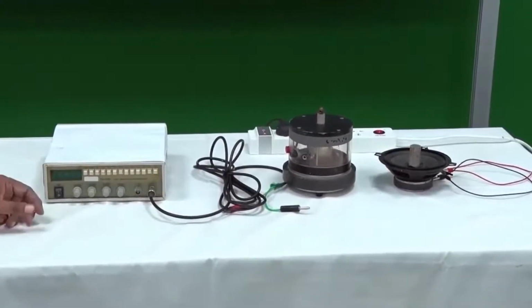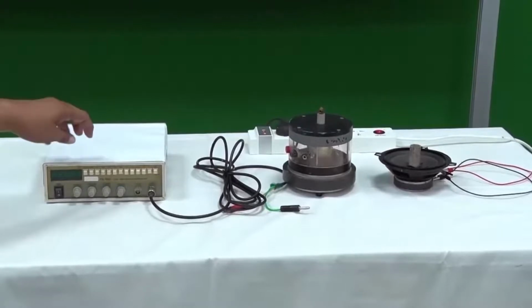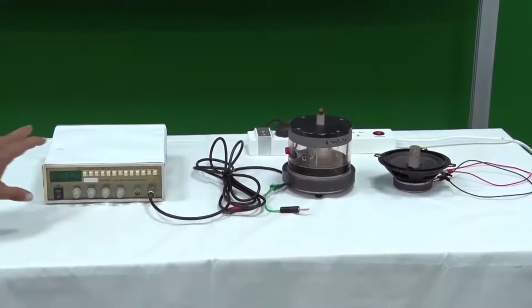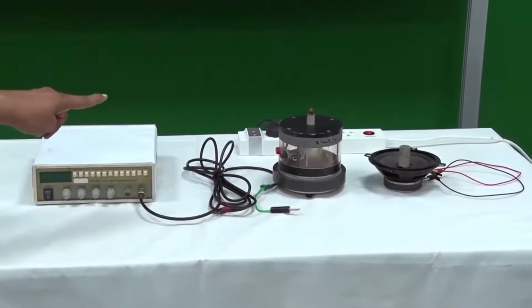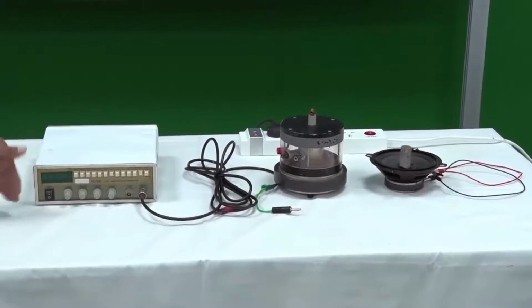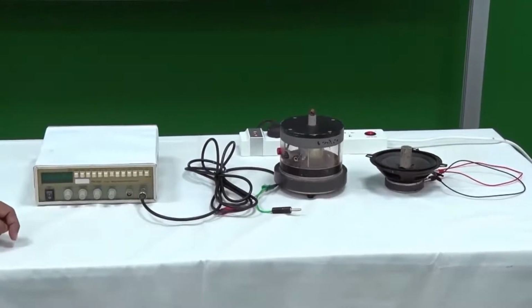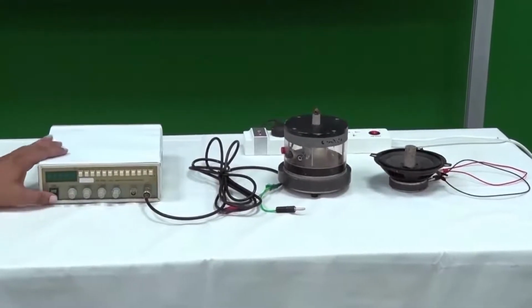So, we need DC voltages, but still we are using that power, 220 volt and 50 hertz. But that is because we do all our DC conversions in this unit itself, otherwise we would have to carry batteries, etc. So, it operates on AC, but it is not using that AC, because that AC is 50 hertz only, and it is producing its own AC at a very different frequency, derived from the DC voltages which are converted from that AC from the power supply, and then that DC is actually used for this oscillator circuit. So, if I put it on,